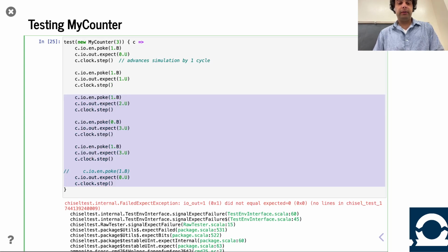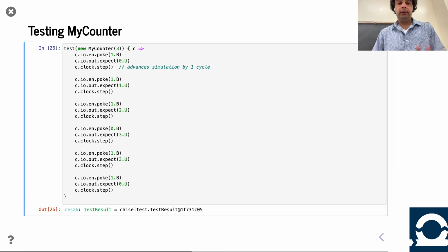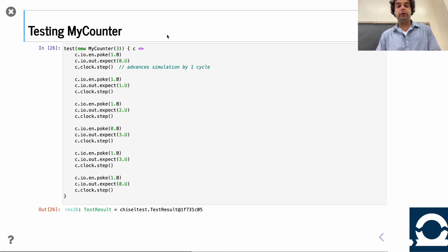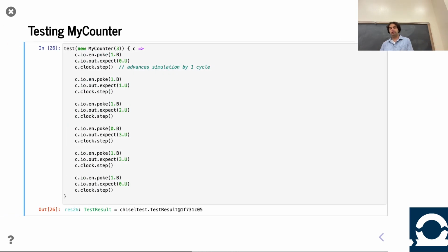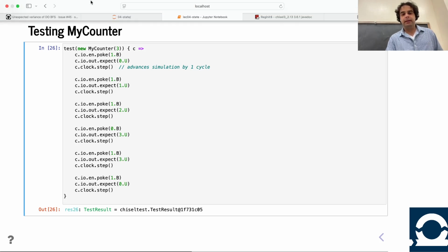Cool. Other questions? Great. Working again. Cool. Okay, so we've built a counter. Kind of recap where we are. We've built a counter two different ways. We've seen this register construct in practice. We say we want a register, we declare it, we wire it up, and these different nuances of reg init, reg next, reg enable are just ways to get some of that stuff, in terms of reset and write enables, included for free, but aren't strictly necessary, just a way to make the code a little bit more concise.